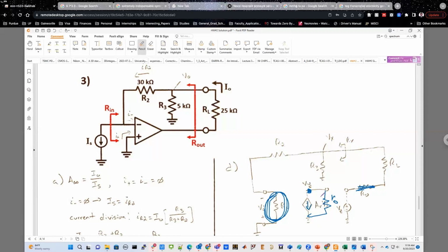You'll see that you reach the same beta factor, or the same beta value, irrespective of whether you consider the voltage source or current source. But if you consider the current source, the resistance will be in parallel, not in series. Questions? That's AP, say AP. If you consider it as a dependent current source, it will be AI. What I did is that I just overwrote what was given earlier, right? So of course, it will not give an AV anymore. It will become AI because you're considering a current source. But good point.